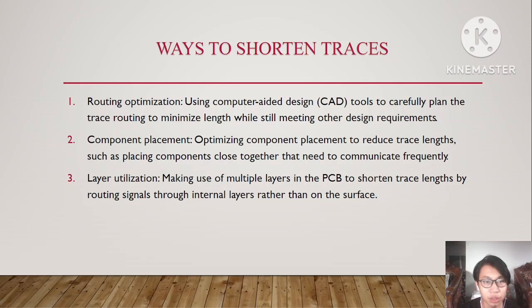And third, we can use layer utilization, where we make use of multiple layers in the PCB to shorten the trace length by routing signal through internal layers rather than on the surface.